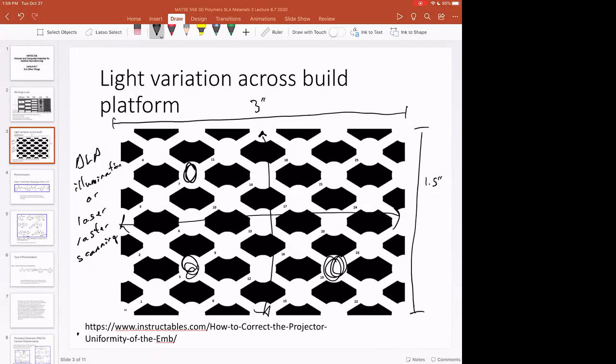And right now, people are working on printer control software for catching these differences and illuminating the bed differently at different times in the print. In a lot of instances, that's baked into proprietary build software. But those are some of the effects that advanced SLA software is trying to combat as the printing speed goes up, as the resolution requirements increase, and as SLA gets more sophisticated in terms of printing final parts with engineering properties rather than just printing prototypes as in the past.